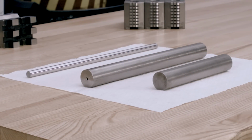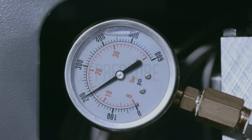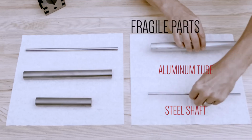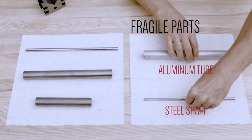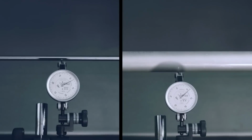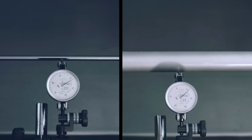But what about parts that deform easily? To recap, for stout parts, we just recommended a tailstock pressure of 200 psi as a good baseline. But with fragile parts, this doesn't always work. Here we have a 1/4 inch diameter steel shaft and a 49 thou wall 1 inch diameter aluminum tube. How much pressure will it take to deform them? Starting with the parts held at 100 psi, we'll measure runout at the middle of each part as we make 100 psi tailstock pressure increases.